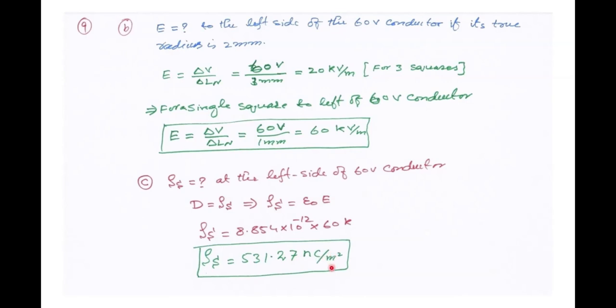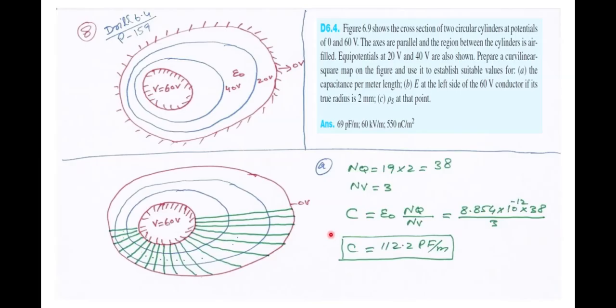So using this approximate graphical method, you can easily define the capacitance between any two conducting boundaries of any shape. You can even include the non-linear effects produced at the edges and corners of the conducting plates.